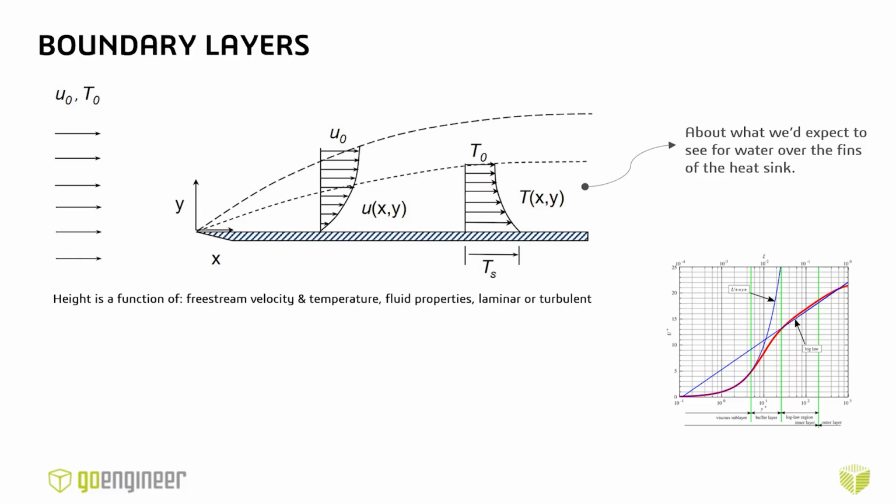This picture here, I pulled it off of Wikipedia, but this is a boundary layer, where the velocity in a free stream flow up here at the top is lowering down to about 0, or exactly 0, at the wall. And there's a sort of profile in how that grows from the wall to the free stream. There's a similar idea for temperature gradients. There's a thermal gradient boundary layer near the wall.